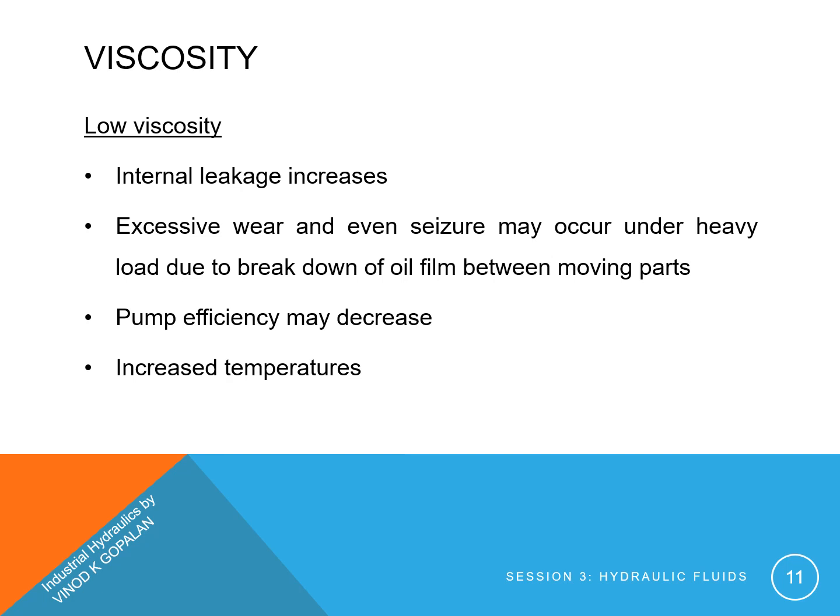If the fluid viscosity is low, internal leakages increase. We know that one of the functions of hydraulic fluid is sealing, filling the minute spaces between the oil seals and moving parts. If the fluid viscosity is very low, this function will be comparatively less effective, which makes increased internal leakages.